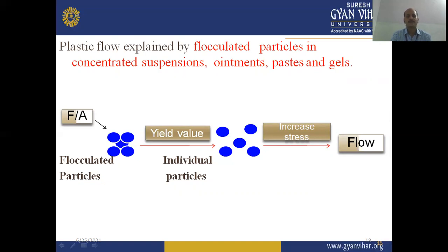When we apply force per area, the shearing stress, the flocculated particles segregate and disperse. The individual particles can be segregated after applying a shearing stress exceeding the yield value. When we increase the stress, they show flow behavior like Newtonian liquids.